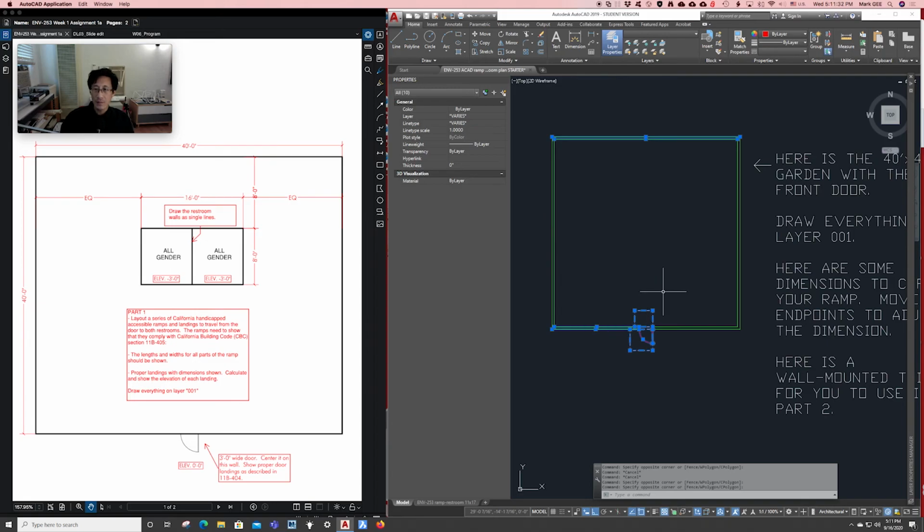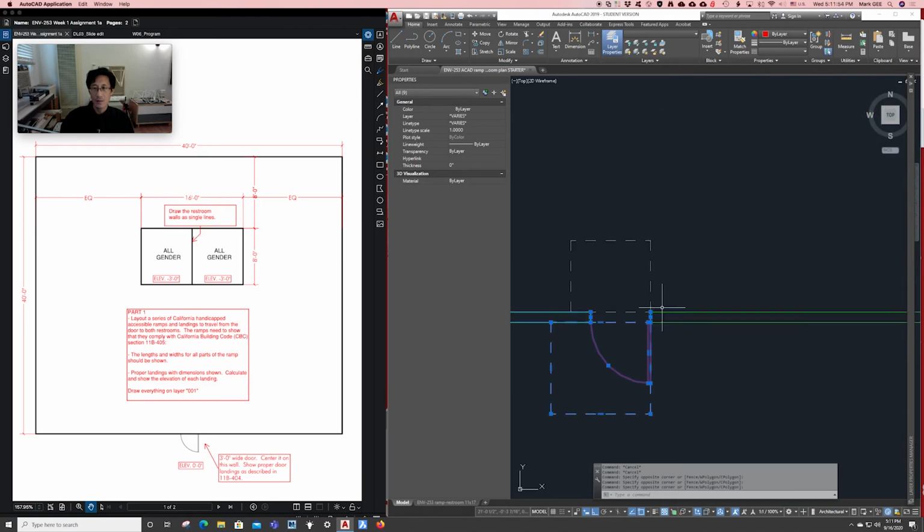To deselect these, I can use the same left to right or right to left picking techniques. Let's do a right to left and deselect this box here. So I will hold down the Shift key, click, release, move the mouse, just touch that box there, click, and you can see that's deselected there. Zoom in, you can see that's deselected.